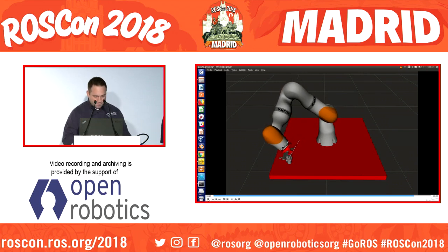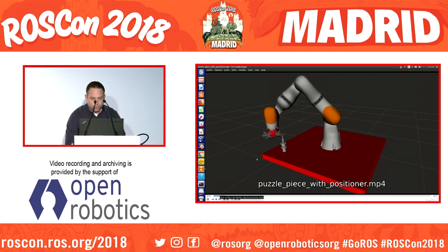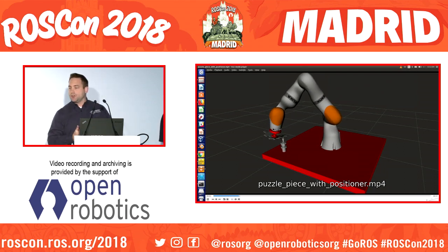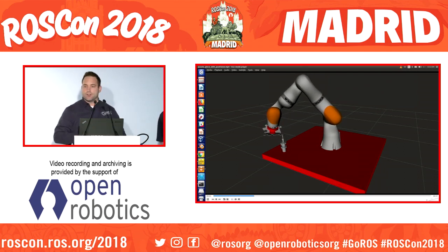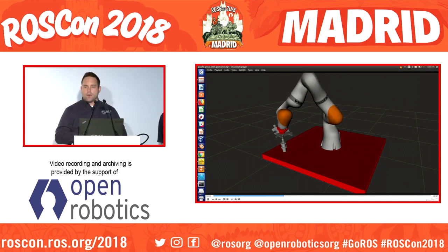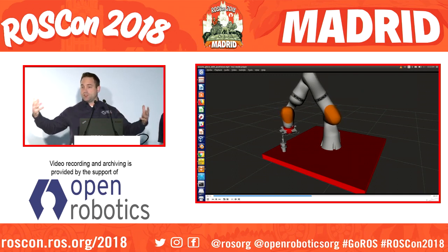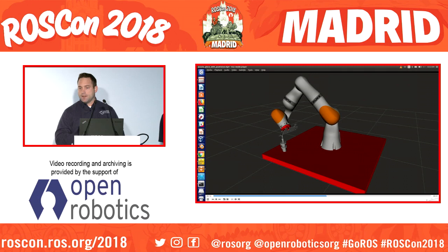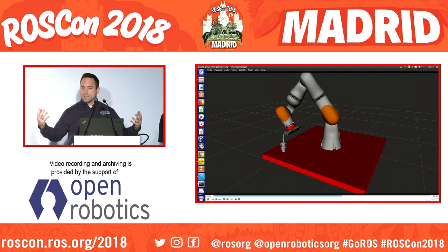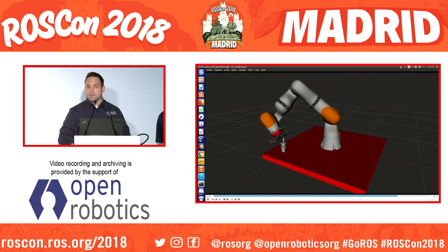And then we have another one just to show that, so we added more. So say you have a positioner. You have a 2 degree of freedom positioner that allows the spindle to move. You want to solve that all together. So we created not only kinematic chain type capabilities, but an arbitrary joint tree to be able to solve that. So say you have multiple robots in your environment, and you want to optimize them all together for a complex process. By using TrajOpt along with Tesseract, you have the ability to do that.